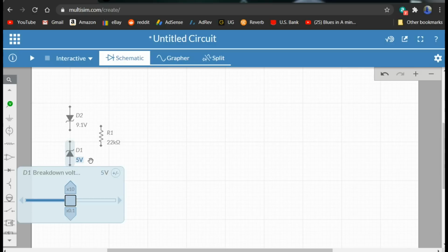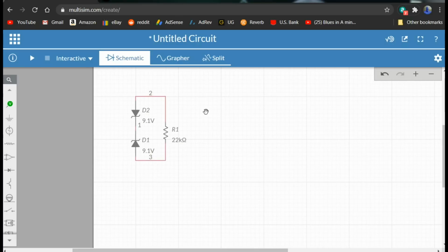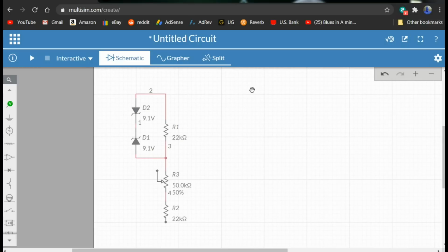That's going to cause the resistance of the negative feedback to decrease, and more negative feedback is applied to the op amp, and that will help us control the output voltage a fair bit. So that's what I'm drawing here. The second change is a potentiometer to adjust the negative feedback again, just to help smooth things along. Otherwise, it's the same circuit.